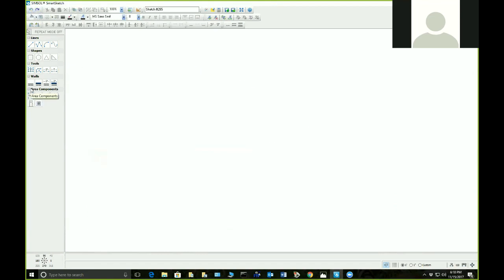And then I'm going to go to walls. Now, if you're drawing just regular walls here and you don't want dimensions, I'm just going to make sure I have my vertical horizontal snap turned on, and then I can draw it. As you can see, there's no dimension on it, but I can always use the pointer tool. The pointer tool is one of the most important tools in the drawing program because that marks the object. So if you just come over here and hit the pointer tool, select it, then you're going to see what that length is, and then you can readdress it if you need be. Okay, so don't forget about the pointer tool.